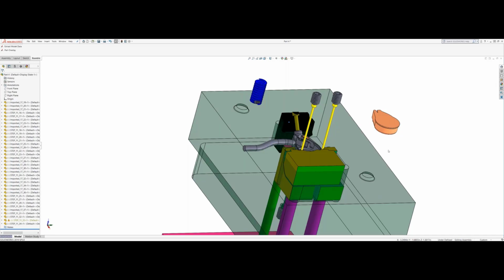So that's a big price driver for piece price. If you're looking at higher volumes, typically 1,000 pieces, 1,500 pieces or more per lot size, you want to look at automated tools if you have actions and can't get away from them. Now, if you're running lots of 100 or 50, a manual tool might be the cheaper route.